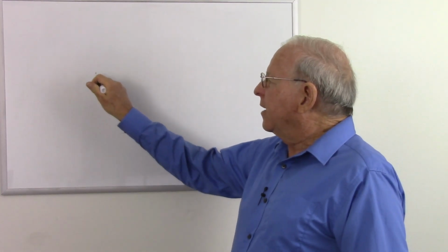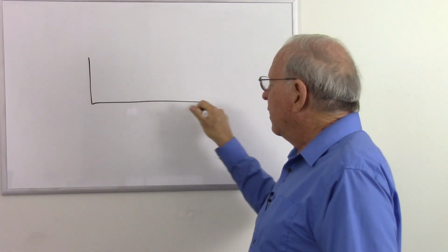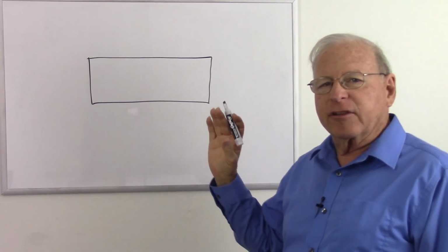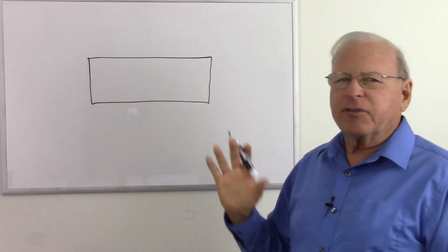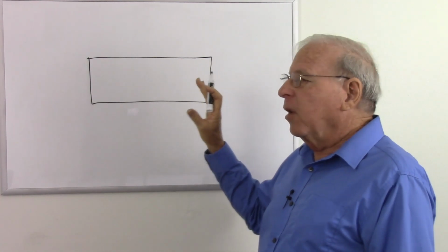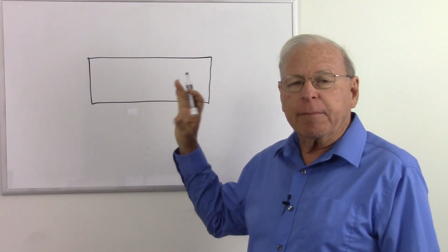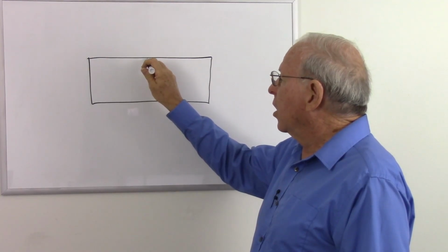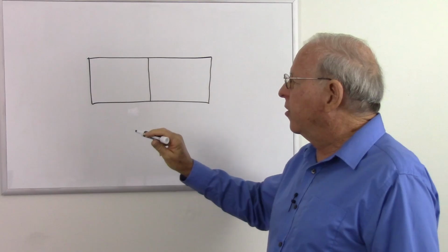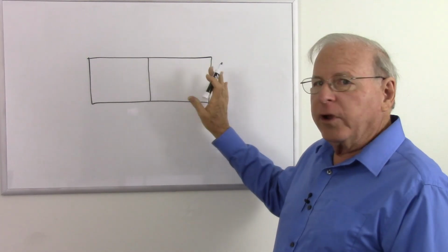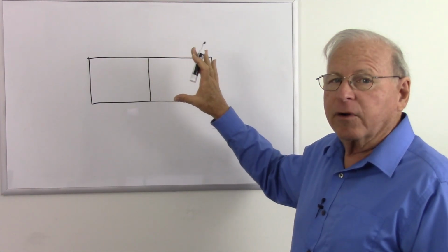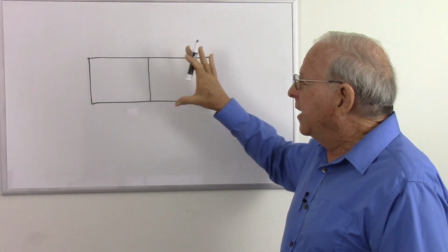So, we know that solid-state devices are typically made out of silicon or germanium, which forms a crystal structure that is not conductive. We call them semiconductors, but when they're in a crystal form, they're not conductive. But we can diffuse impurities in there that make them conductive. So I'm going to draw a line here because I'm going to have different impurities on the different sides. On the right side, I'm going to infuse impurities such as arsenic or antimony, something that is going to add an extra electron.